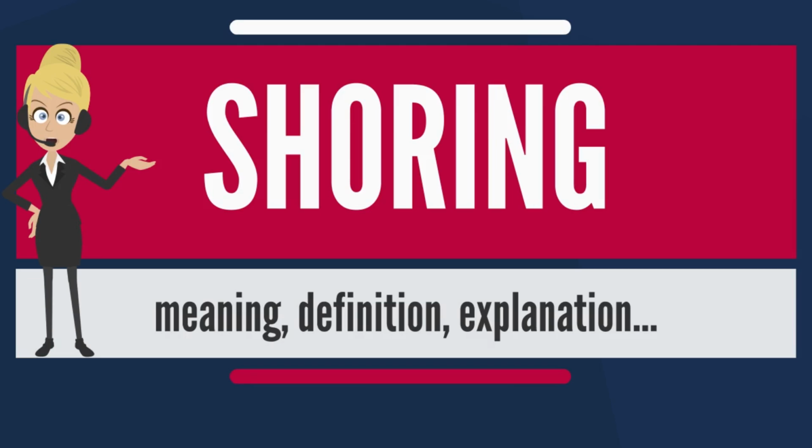Soil nailing is a technique in which soil slopes, excavations or retaining walls are reinforced by the insertion of relatively slender elements, normally steel reinforcing bars. The bars are usually installed into a pre-drilled hole and then grouted into place, or drilled and grouted simultaneously. They are usually installed untensioned at a slight downward inclination. A rigid or flexible facing, often sprayed concrete or isolated soil nail heads, may be used at the surface.